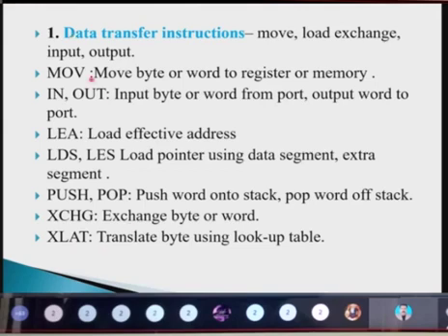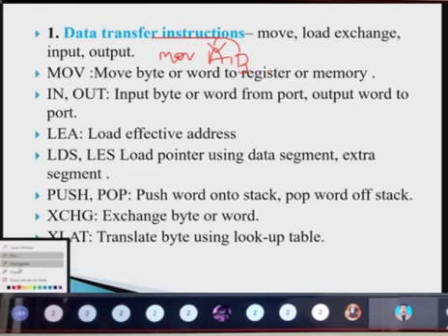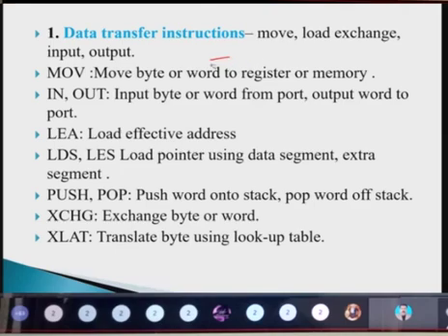So using these instructions, we can add the data. Okay. So for using this move, if I'm just telling move A comma B, in the sense whatever the content stored in B, that will be moved to A. If I'm using move R1 comma R2, it means from R2 the content will be moved to R1. So that is the meaning of that one.